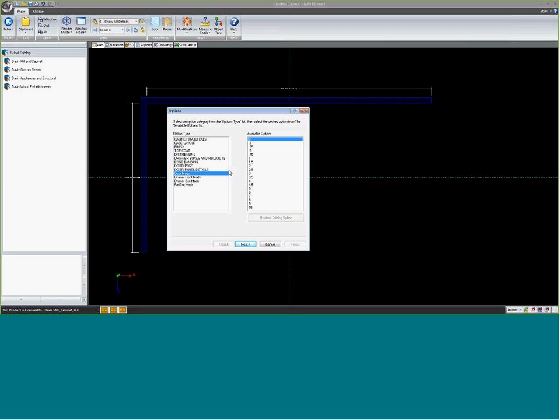We'd say, oh yeah, that's fine, we can do that. However, you need to put in a 0.5 door. That will add a half an hour labor to every door on the job. That's how this calculates. But typically you'll just ignore these last four. But if you have something weird, talk to us and we'll tell you what mod to put in there. So that's your basic options list.